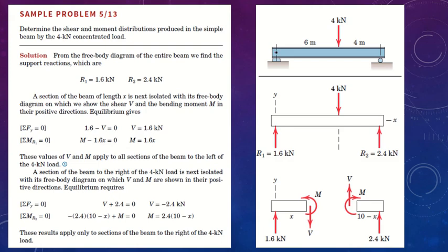First thing is, we are going to draw our direction vectors. Sorry if my representation is not very accurate, but I hope you get the idea. So this is the y-axis, this is the x-axis, and this point is the origin, the pin joint. From here, assuming the sum of moments about point 1 is equal to 0, you have 4 kN acting downward. This is going to create a clockwise moment, and R2 is going to create a counterclockwise moment. They should be equal and opposite. As the system is in equilibrium, you can find the value of R2.